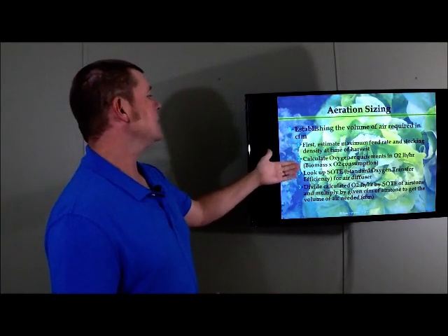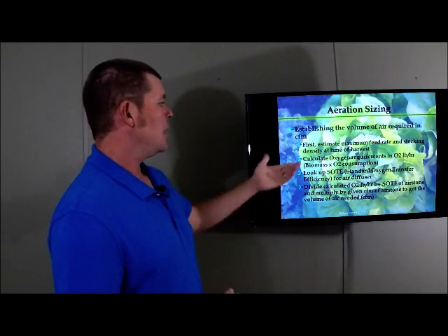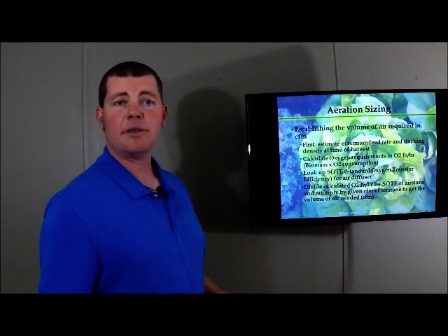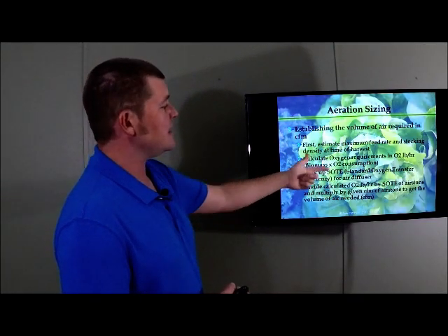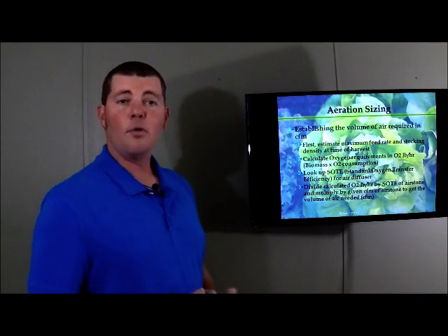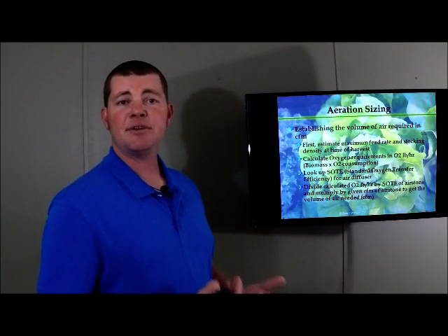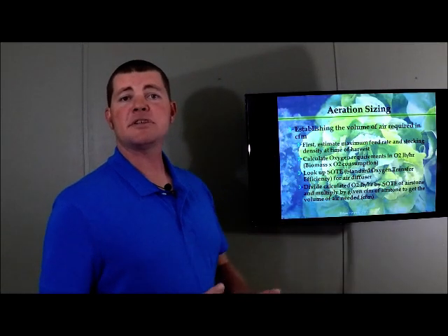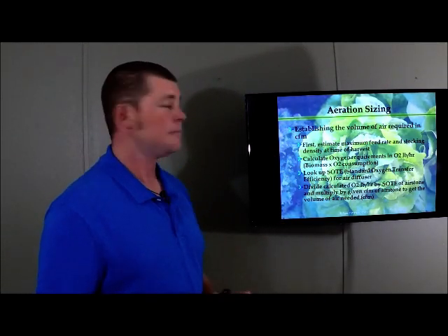Then we can calculate the oxygen requirements in pounds of oxygen per hour, and that's biomass times oxygen consumption, and we've already done that. We look up the SOTE, which is the standard oxygen transfer efficiency for the air diffuser that we're looking at using. So it tells us the efficiency of how many pounds of oxygen we're injecting versus how many pounds are actually getting dissolved into the water column.